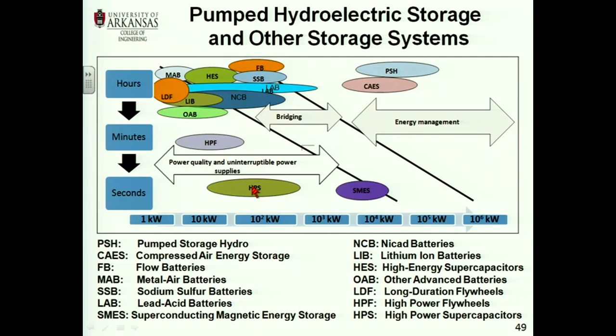The capacitors don't like the change of voltage, right? And they are used as filters where you don't want the voltage to change. Normally they are the output of your converters, because you want to have a stabilized DC bus.